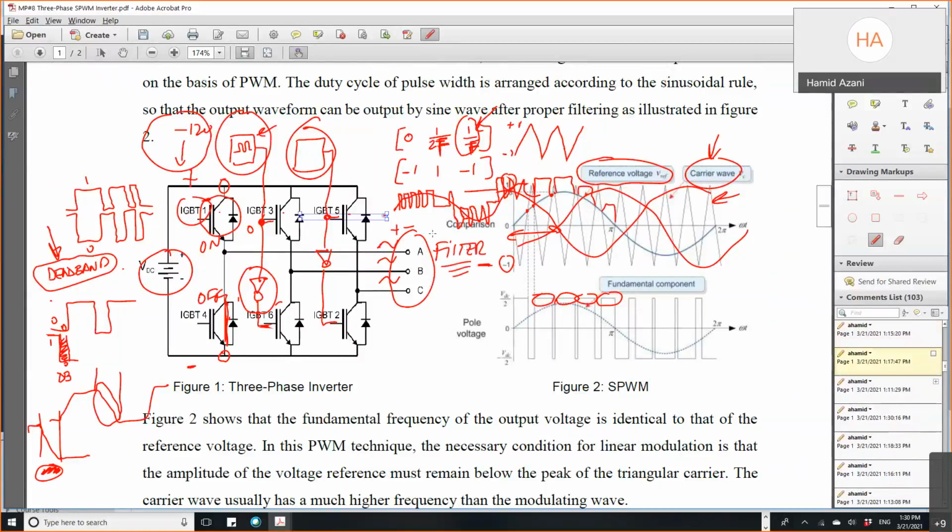I'll let you investigate this part. Add a first order filter, for example, to keep only the fundamental, and you can get your three-phase signal after that. You can plot before and after the filter and compare them.